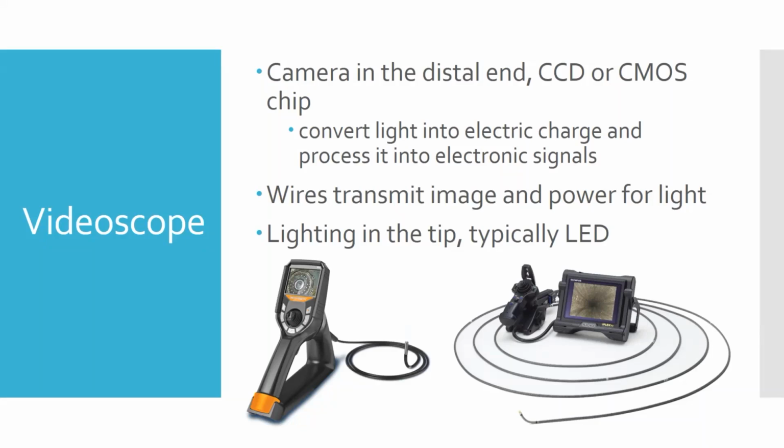So when we talk about infrared thermography, you can actually perform borescope thermography, kind of combining. Or they can put an ultraviolet or black light LEDs in the tip and be able to go inside of objects where they're doing dye penetrant or magnetic particle or different types of leak check dyes and see the signature of those. So you can start to combine some of these, and they're pretty cool. So they're pretty high tech.